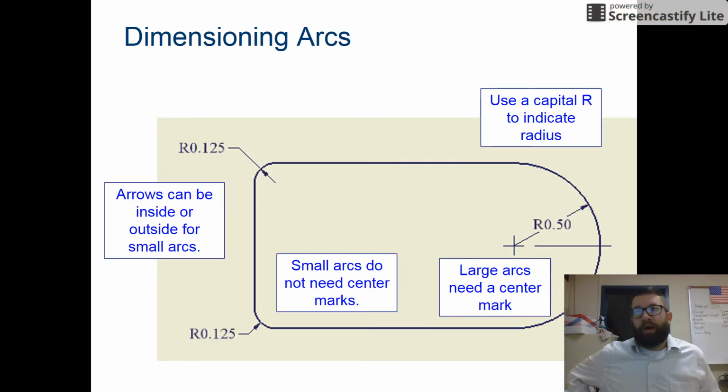All right, so we're back with part 2 of dimensioning standards for Unit 7 of IED. So we left off with talking about arcs. So your arrows can be outside or inside for the small arcs, and they don't need center marks. Large arcs probably should have a center mark.